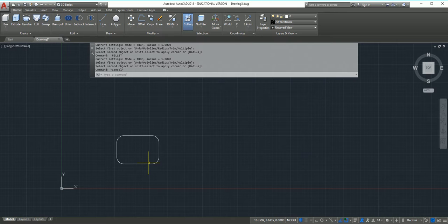This is where the shortcut commands come in really helpful because your toolbars are different, right? If you have the shortcut command, it makes it a lot easier. So the shortcut command would be REC, or you can type out the word rectangle. What was it? 4 by 6, wide 6, high 4. Doesn't necessarily matter, but it's fine.